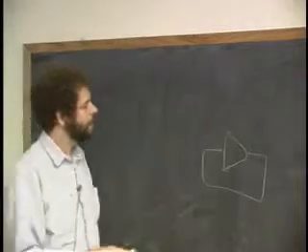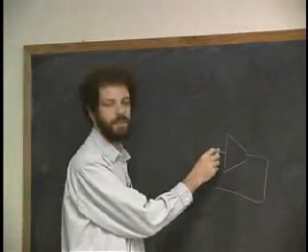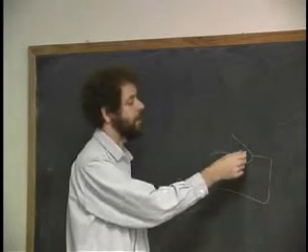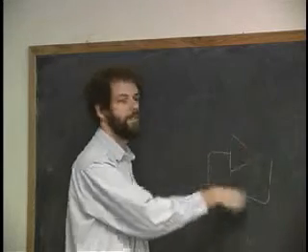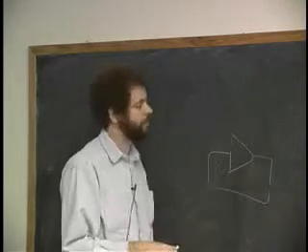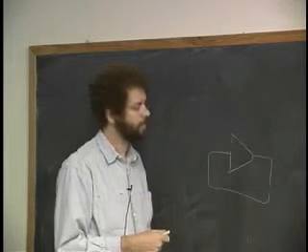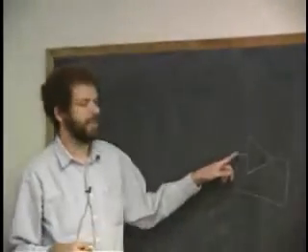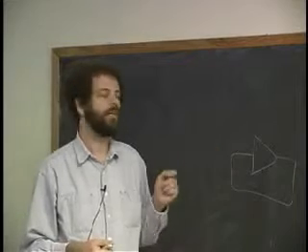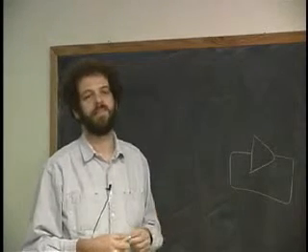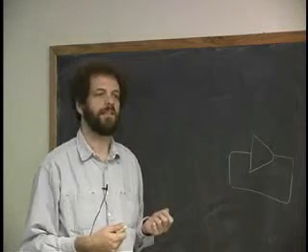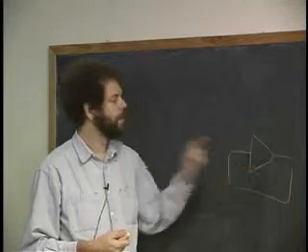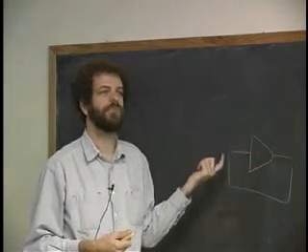So sure, you could say, yeah, if there's a modestly high voltage here, because the logic element itself improves the quality of the signal, it'll make a higher voltage over here. And that'll go around and around and around until we get stuck at a voltage which is nice and high, and it'll stick there. But let me ask you a philosophical question. Why can't this device, which is latched in the high state, suddenly decide, you know what? I've changed my mind. I'm going to latch in the low state. Have we really explained, other than saying that instantaneously this takes some voltage over here and transfers it to a voltage over there, how this thing remembers?